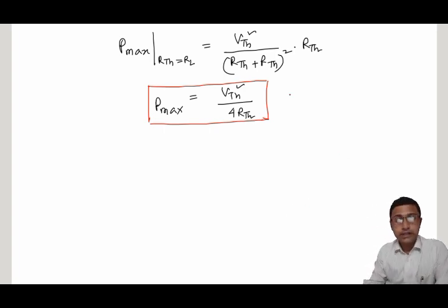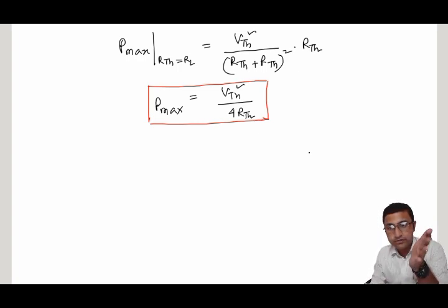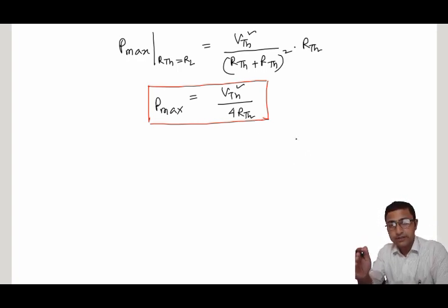If I consider the same problem that I have already solved using Thevenin's theorem, step 1 and step 2, that is the Thevenin equivalent voltage and resistance, VTH and RTH, are the same as in Thevenin's theorem to solve a network using the maximum power transfer theorem.